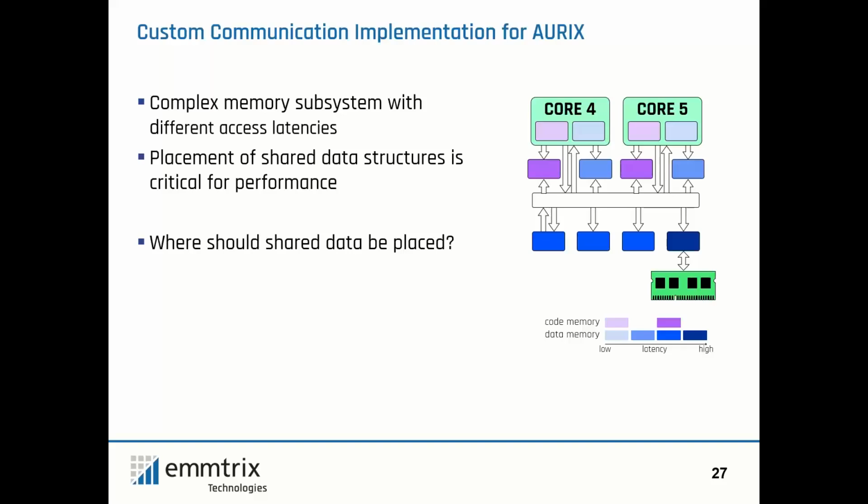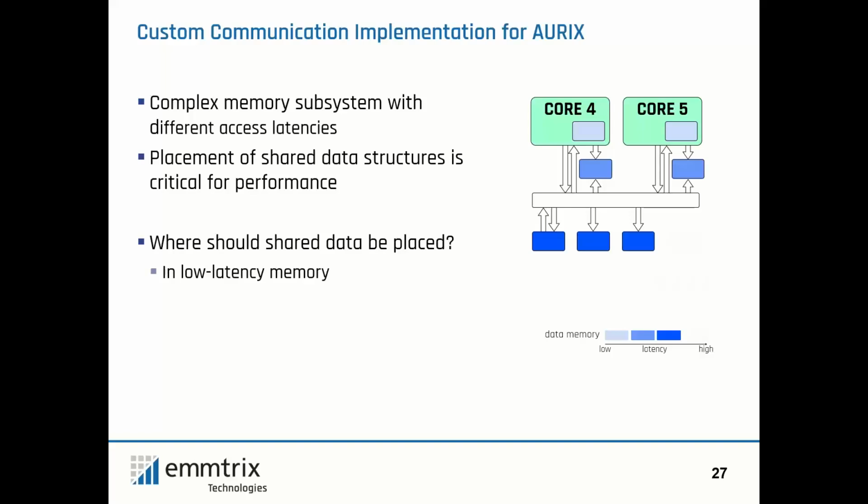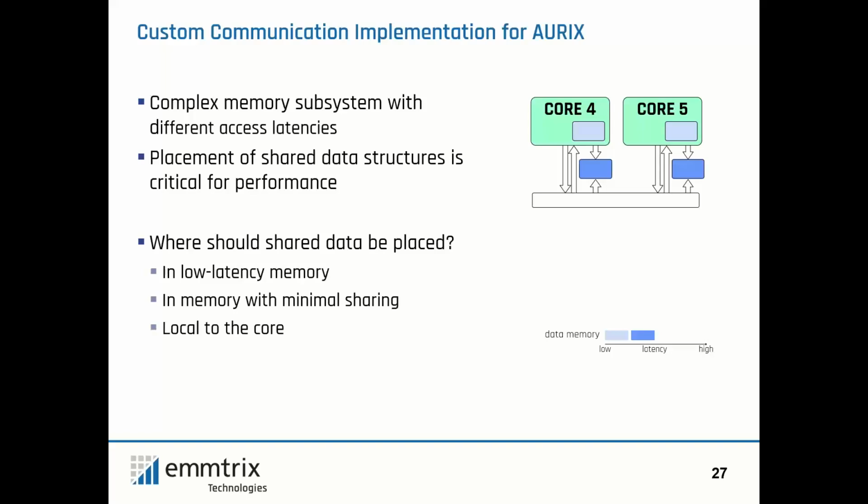So the question was, where should the shared data be placed? We won't place it in code memory because it's read-only. It should be put in low latency memory, so any external memory is out of the question. Also in memory with minimal sharing, which means that the shared memories are out of the question. And it should be local to the core.